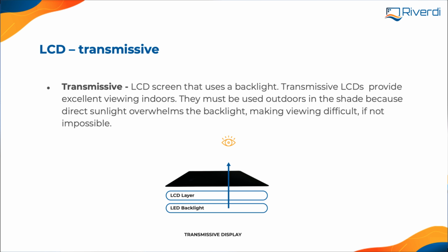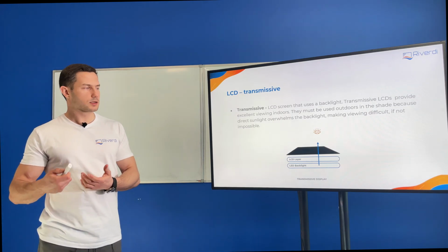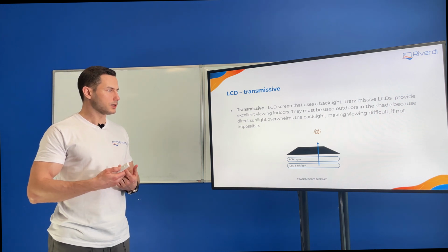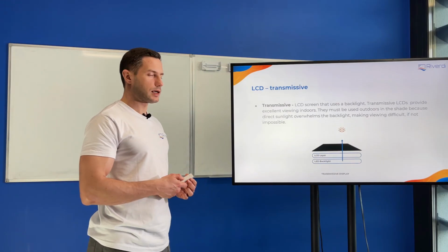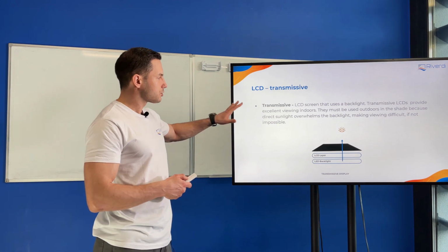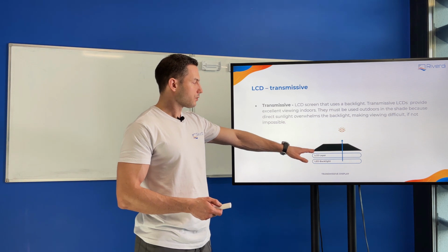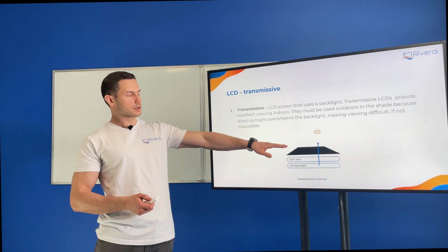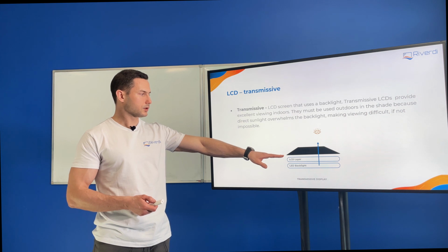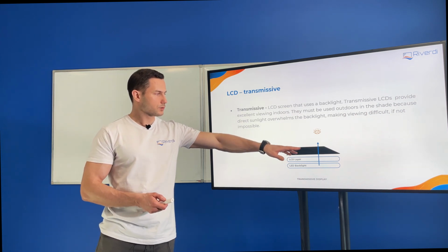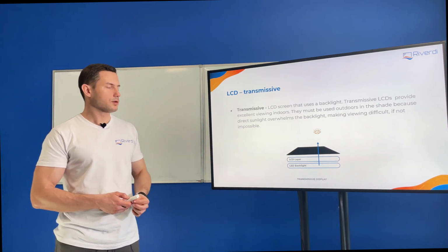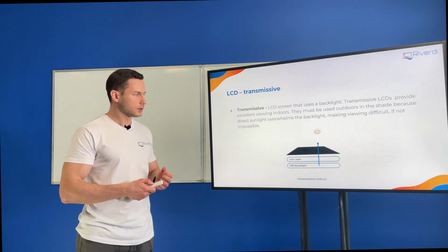Okay, now we will talk about three different technologies used in monochrome displays, how the light is being transmitted, and how we see the image. Yes, so the most standard and common display would be the transmissive display. So we have a transmission of the light from the backlight through the LCD. As we said, the LCD will have polarizers, LCD glass, another polarizer, electrodes, and then we have the surface of the screen, this black part, and we have the viewer, the user that is seeing the screen.